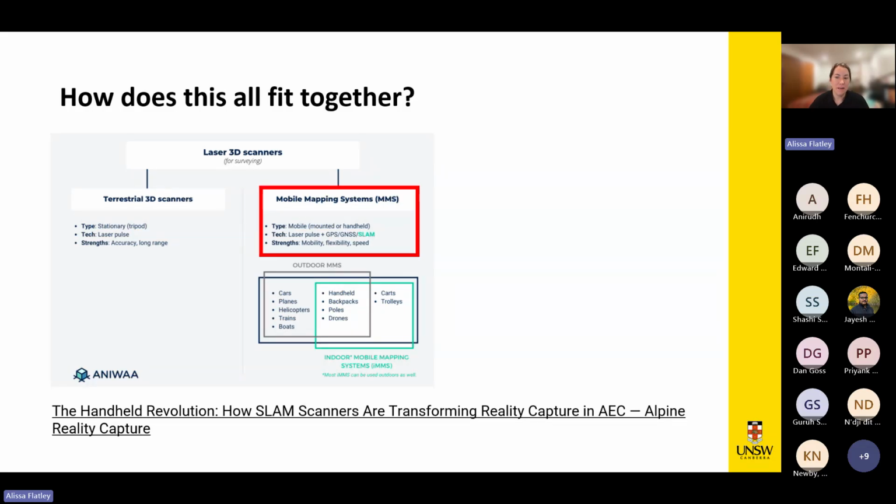To overcome some of these limitations on sort of scale and timing, a lot of terrestrial laser scanners have been mounted on varied mobile platforms, and these are otherwise described in the literature as mobile laser scanners, so MLS, or mobile mapping systems, MMS. So these have been deployed by mounting TLS onto carts, onto vehicles, snowmobiles, survey boats, and sledges.